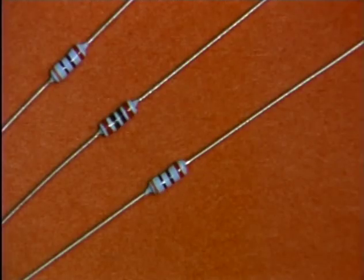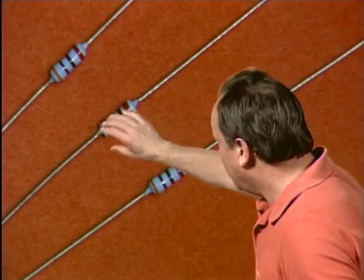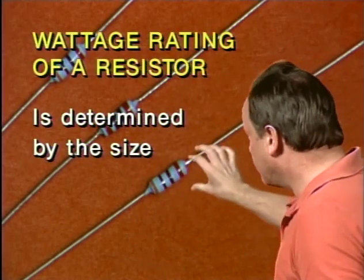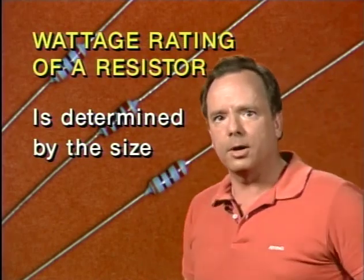Now, resistors have to absorb a lot of electrical power. That's what they're doing, is absorbing and dissipating electrical power. And electrical power is measured in watts. We'll talk more about that later on. So what determines the wattage rating of a resistor? Well, the wattage rating of an electrical resistor is determined by its size. The bigger the resistor physically, the more power it can absorb.